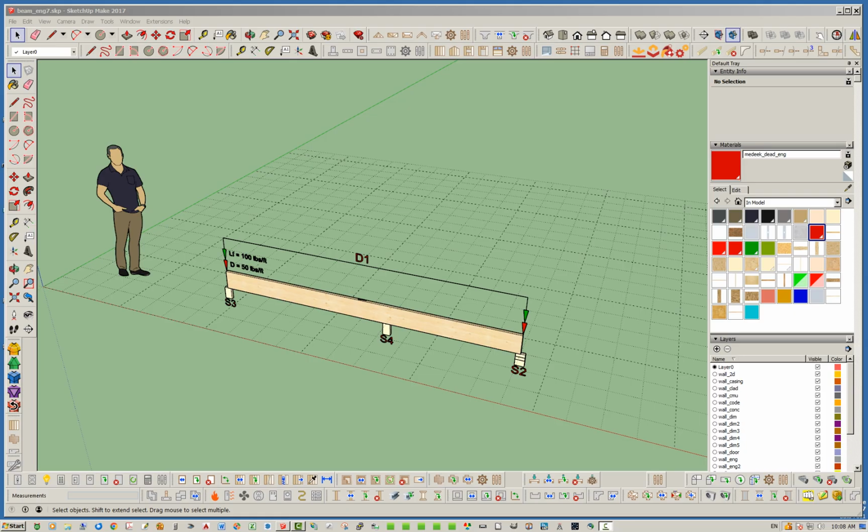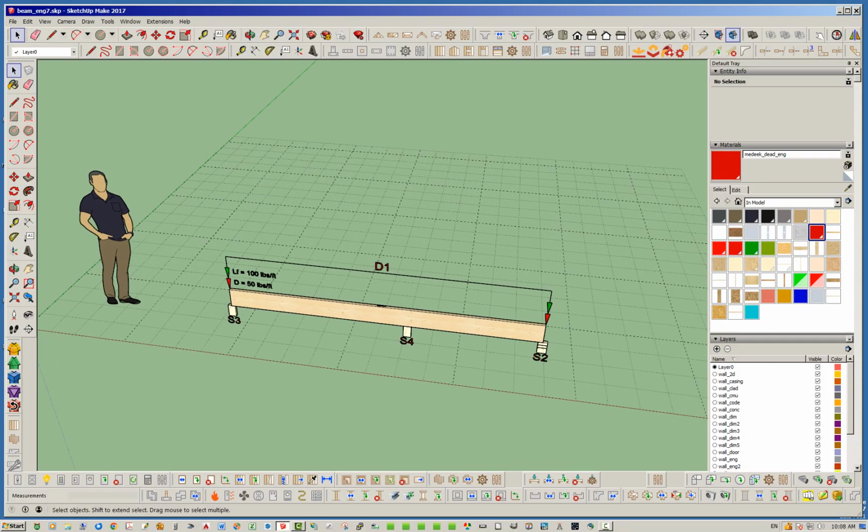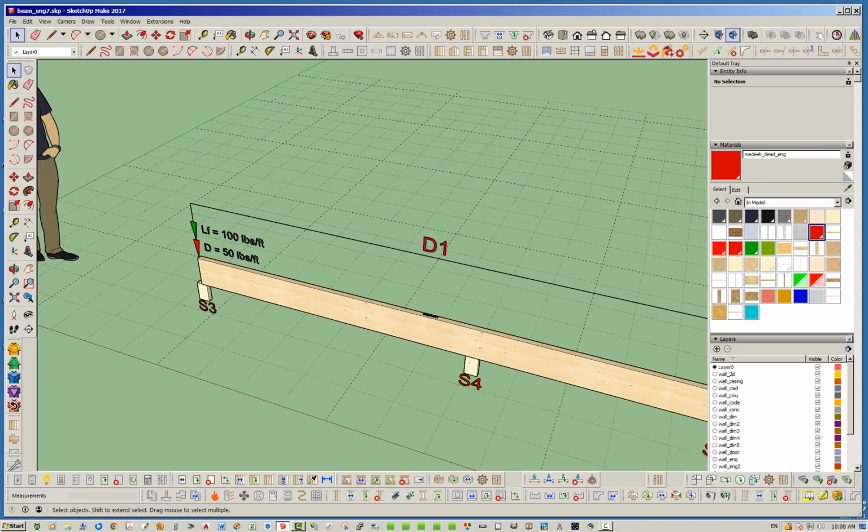here. So basically, when you have a beam, the issue when it comes to bending is that you will potentially get what's called lateral torsional buckling. So basically, as you load the beam in bending or put a load on it, as shown, if the beam is not braced along its length, it will actually fail quicker, usually in buckling, than it will fail from the bending forces alone.